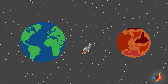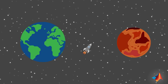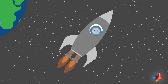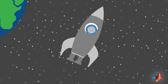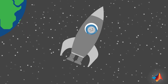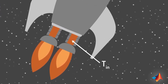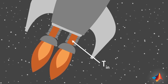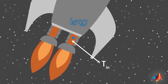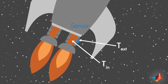But be careful because a too high temperature can put the mechanical components of the engine at risk. And this can lead to the failure of some of the mechanical parts. If that happens, you might be stuck in your small spacecraft where you've got to eat from tubes. To prevent such a situation, you should closely monitor the internal temperature of the combustion chamber. This is not an easy task, since a sensor placed inside the chamber would melt. Instead, it needs to be placed on a cooler surface, close to the chamber.